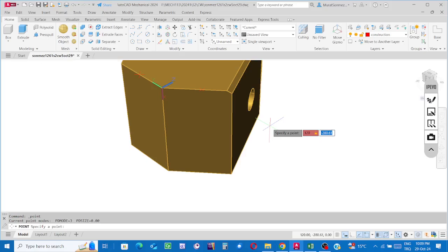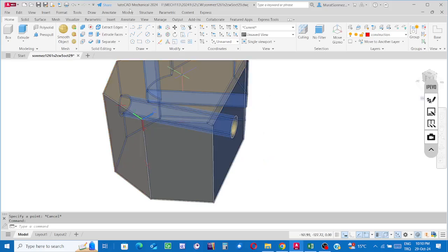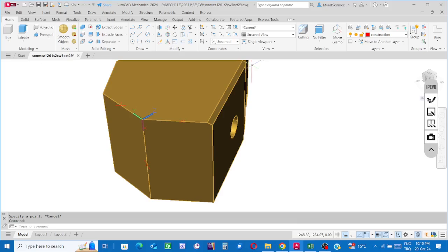Abscissa is 120, altitude is 0. Click on ordinate, it is 0, click on the comma key, altitude is also 0. Press enter. That is the third point. And then the most difficult stage is overcome. That is okay, completed. The rest is polyline, 3D polyline.